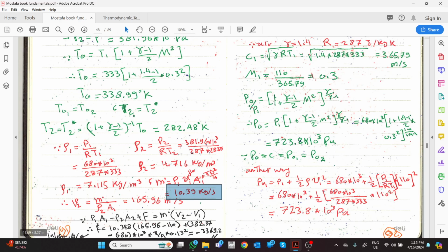If we divide it by area, divide this one by area and ρg, divided by area and ρg, divided by area and ρg, then this one will be pressure by the way, and ρg will become head. This becomes head, head, head. So at the end it will be heads.